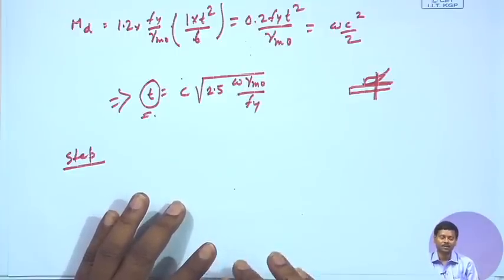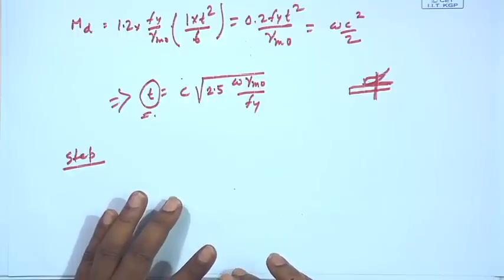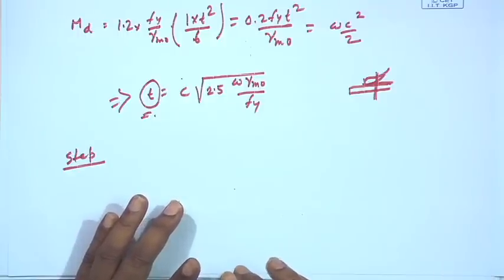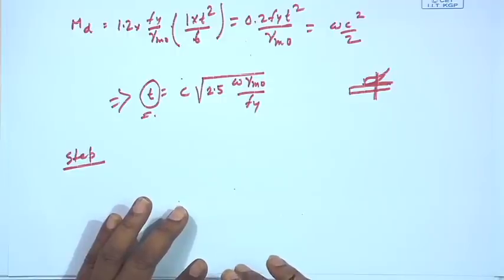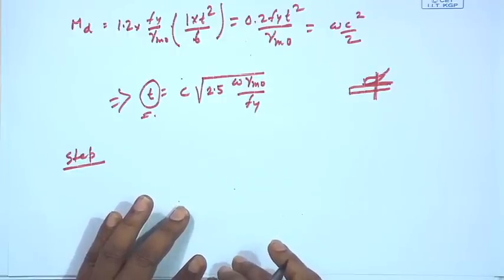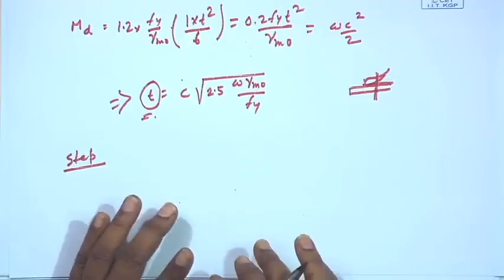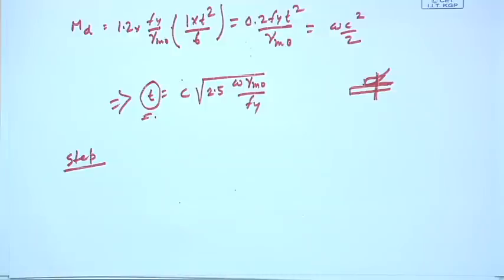Another thing is that when we are going to provide a Gusset plate, we have to know what will be the Gusset plate thickness, and what should be the Gusset plate size, that means length and width. So, these are the few things which we need to know.